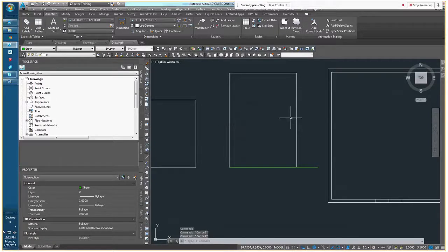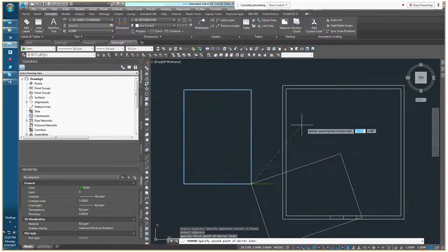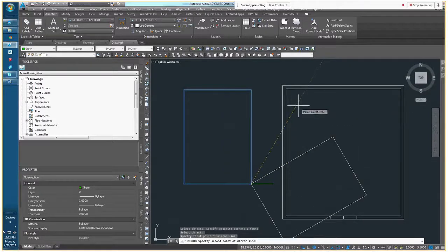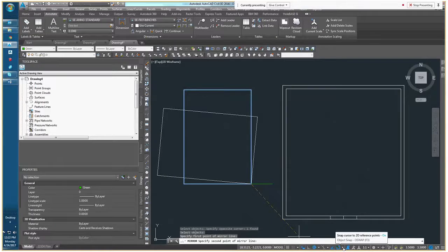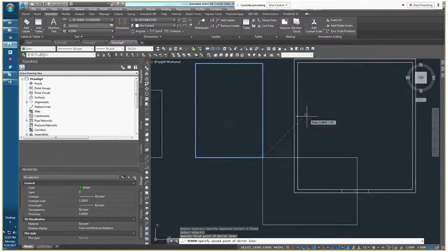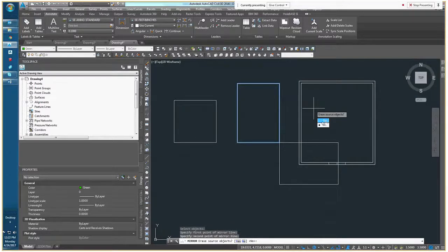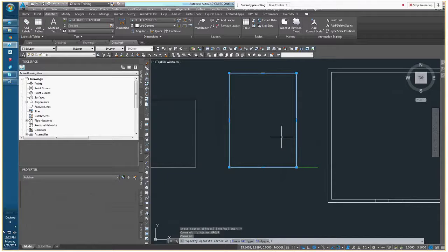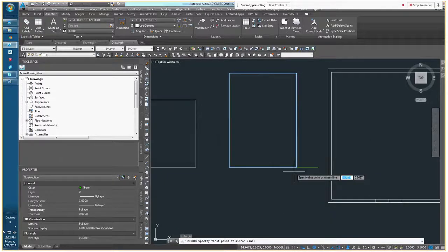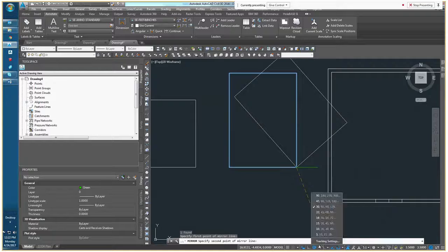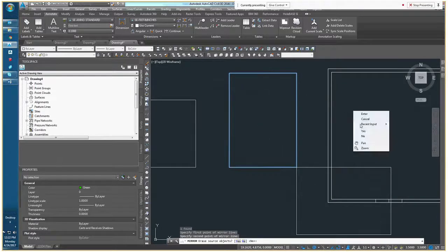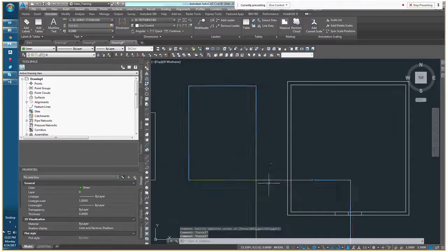The same thing can be done with the mirroring command. If we were to mirror this object, you could, of course, use polar to mirror it based on any of your polar snap settings. Mirroring with polar snap of 45 is extremely helpful when doing certain geometry. So you can see here, it's going to create nice little, comfy little quadrants. When you're doing the mirror command, it also gives you an option to erase the source geometry or not. So you can make copies as you're mirroring things around.